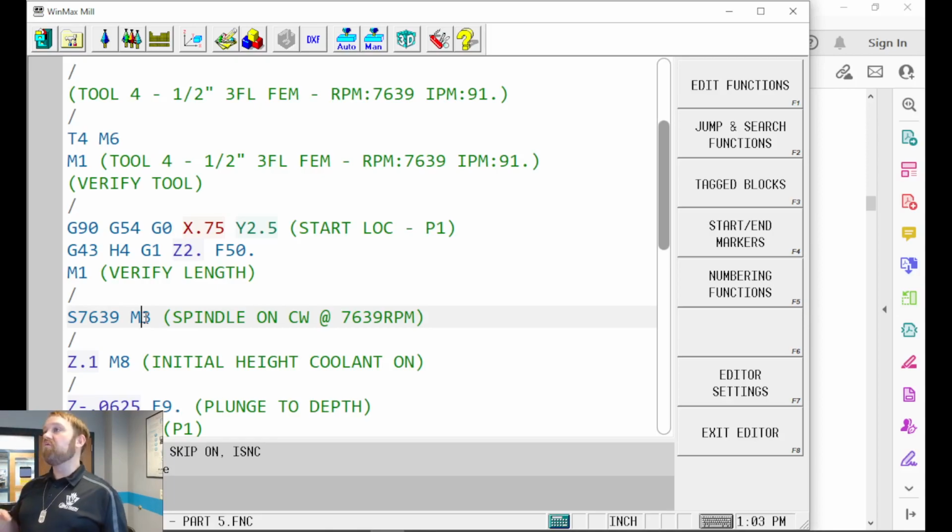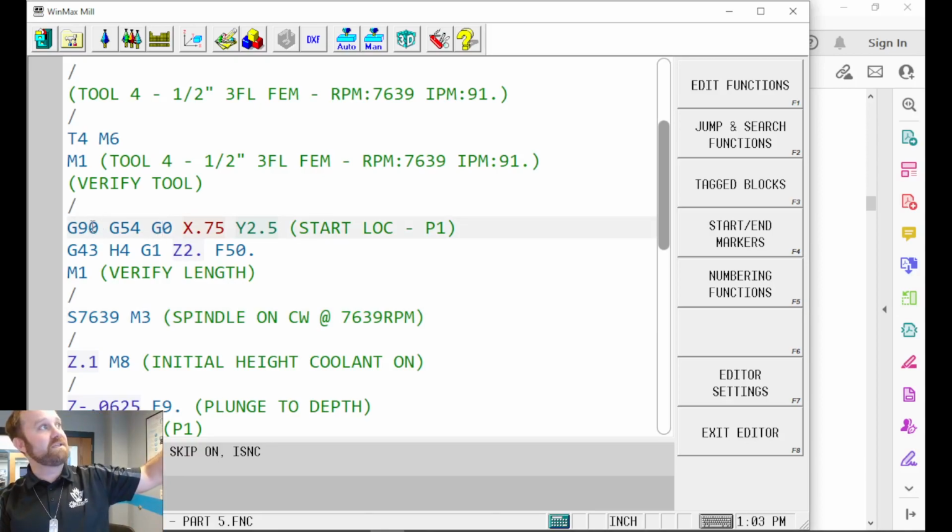If it's a movement type, line, rapid, curve, clockwise, counterclockwise, can cycle, if it's a movement type, it's a G code, preparatory code. Okay, you're basically saying, hey, in this line, you're going to do a straight line move. In this line, you're going to do a rapid move to this absolute value, work offset 1 to X.75, Y.2.5. Okay? All right.